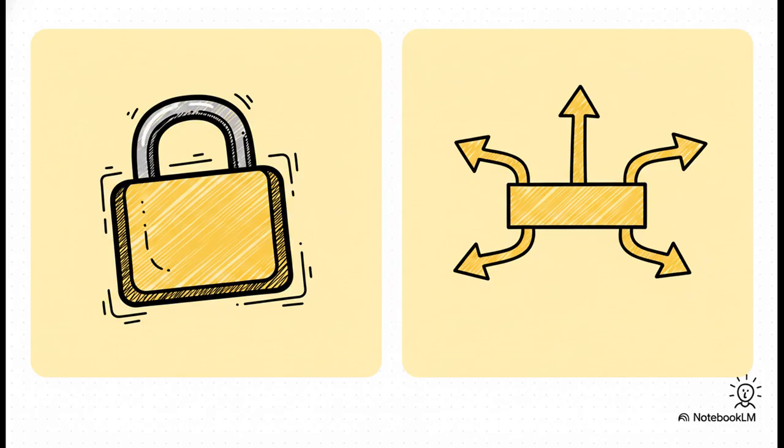Fixed port addressing is hard-coded, sits right next to the opcode, and is strictly limited to an 8-bit number that has to be zero extended. On the flip side, variable port addressing is entirely dynamic, utilizing the full 16-bit capacity native to the DX register.